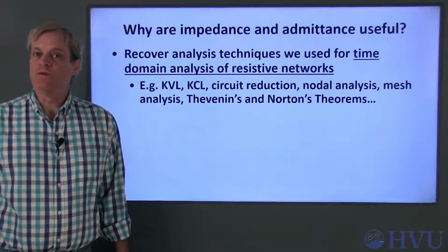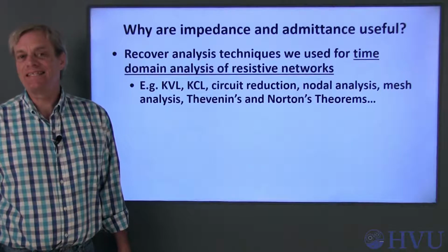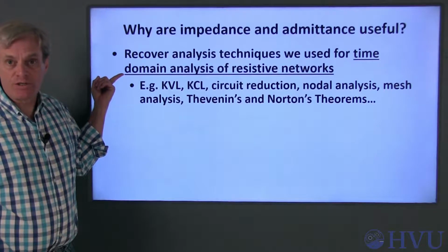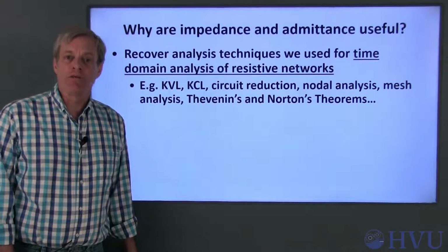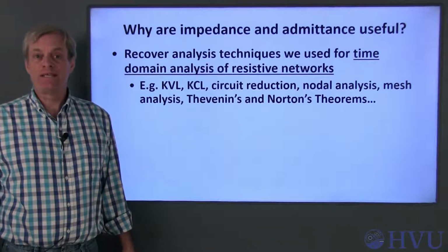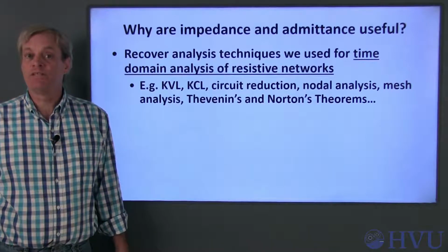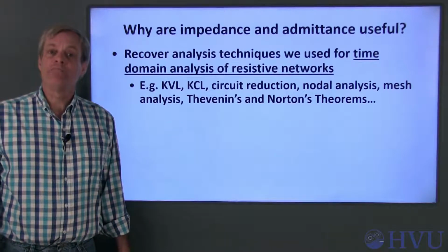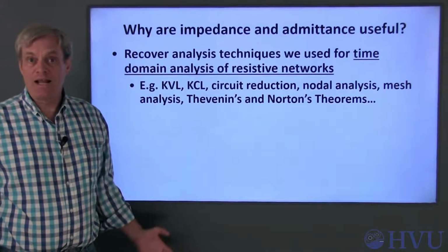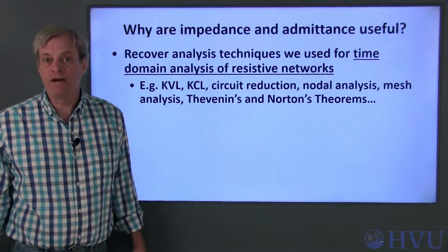Impedance is super useful because if we represent the circuit elements as impedances, we can now do steady-state sinusoidal analysis exactly the way we analyze purely resistive circuits. That means that tools like circuit reduction are now appropriate. We couldn't combine resistors, capacitors, and inductors into a single equivalent element in the time domain, but we can combine different types of elements in the frequency domain if we represent them by their impedance. Likewise, we can use voltage and current dividers, nodal and mesh analysis, and Thevenin's and Norton's theorems almost exactly as we did with purely resistive networks.